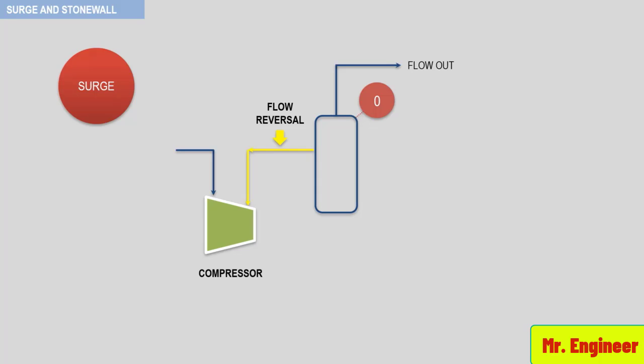Once the vessel is evacuated, the system pressure observed by the compressor rapidly reduces, thus enabling the compressor to achieve a new operating point in the positive region of the performance curve at high flow, and this will cause the vessel to be filled. Once the vessel becomes filled, the operating point moves again up the compressor curve to surge, and the cycle begins anew.